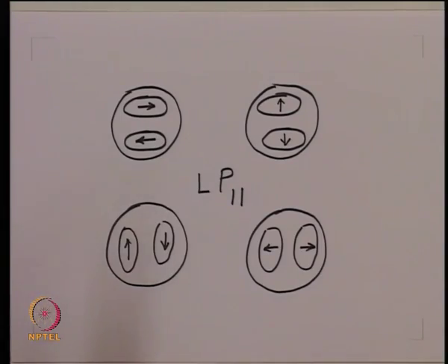So, in fact, whenever we launch a light with arbitrary polarization inside a weakly guiding fiber, and if the excitation mode is LP11, in fact, we have a combination of these four modes which will be propagating simultaneously inside the optical fiber.